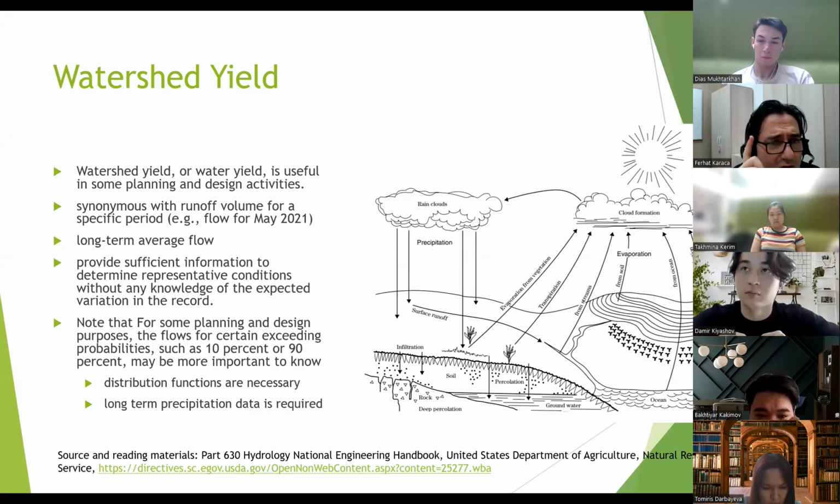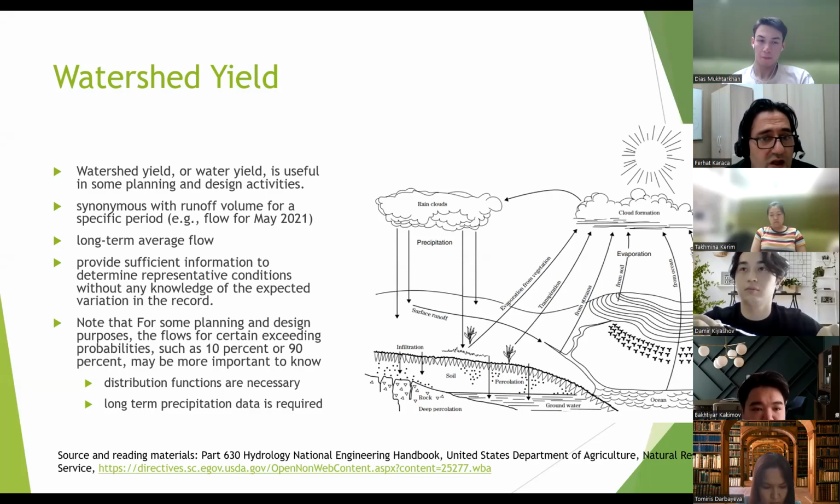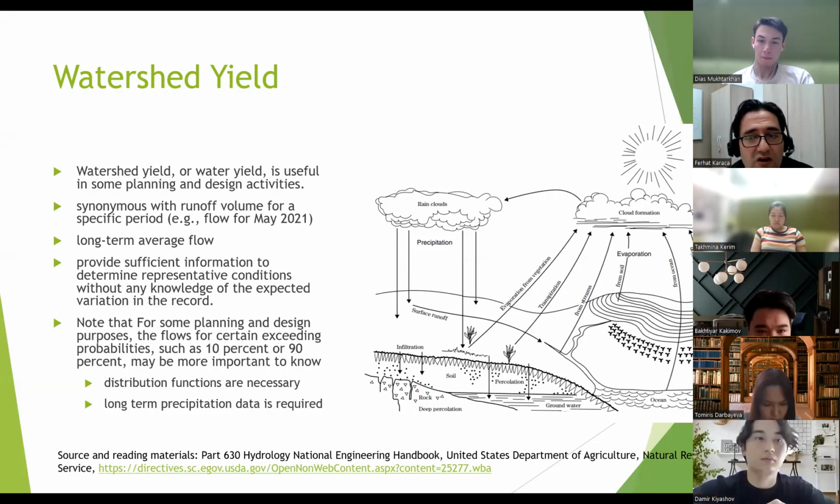And the engineering question here is, a million tons of precipitation you had in the watershed, but how much of that water will be collected in the reservoir? Did you get the trick? In order to know it, you should know the infiltration ratio, the evapotranspiration ratio and some other stuff, and now you are going to learn how to calculate it.